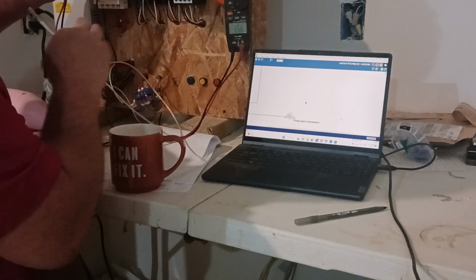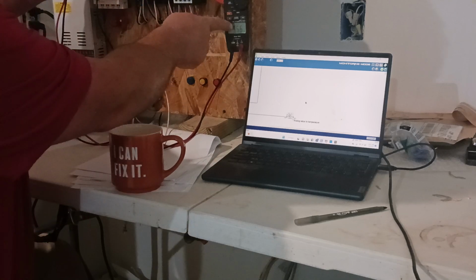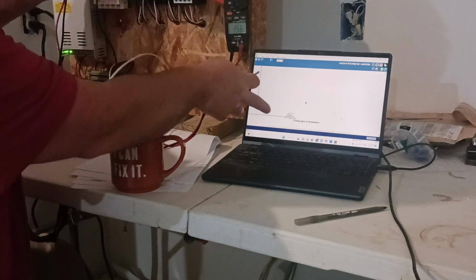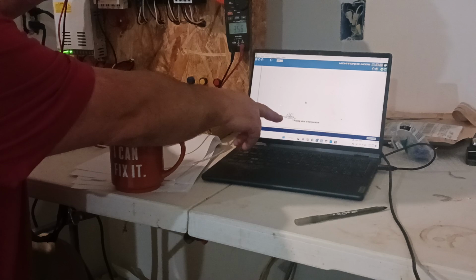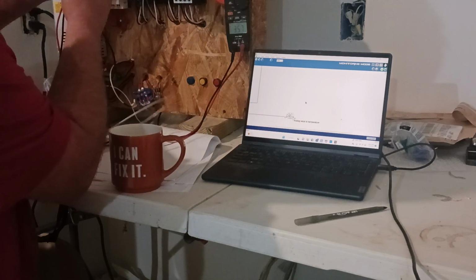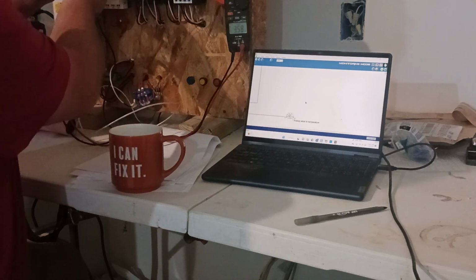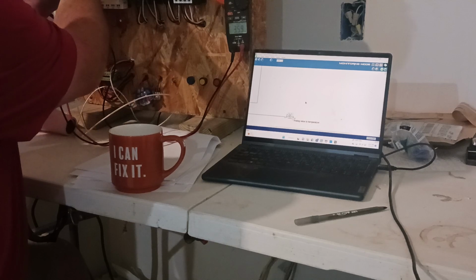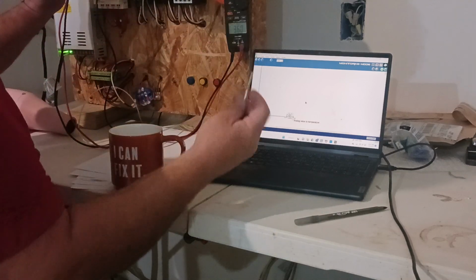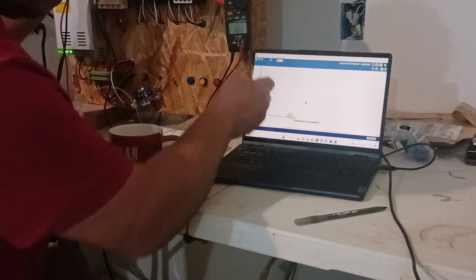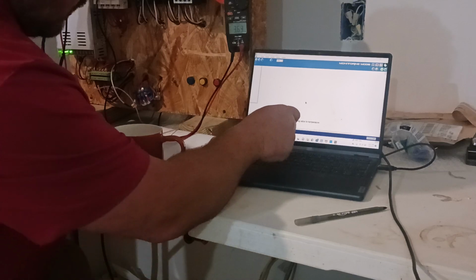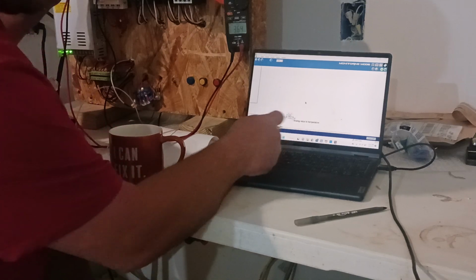Let's just take it out to room temperature. And I want you to watch as this warms up, the voltage will increase and the analog value will increase and the temperature will increase. So you'll notice the voltage increasing. We're out in room temperature. See, we're already at 362, and we're already back up to 66 degrees,